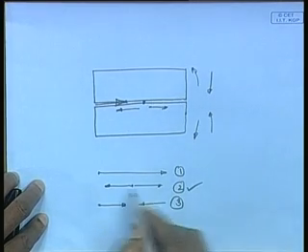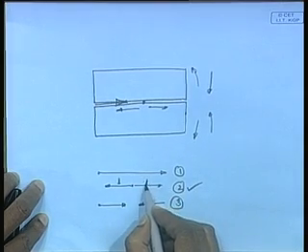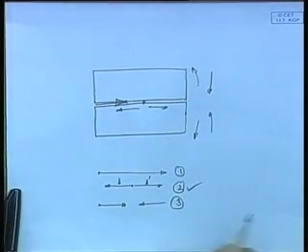Why? Because here the welding run number 1 and welding run number 1 dashed, they are going simultaneously, they are not 1 and 2, they are 1 and 1 dash. By 1 dash I mean they are simultaneous. So, what is happening? The effect of 1 is being nullified by the effect of 2. That is essentially the essence of sequencing of welding. Here we are not mitigating anything, they are self mitigating, they are self cancelling.